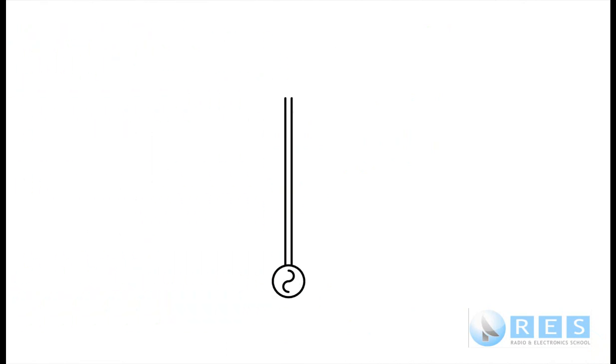Now let's have a talk about some of the antennas that you're going to need to know about for the standard assessment. Before, and I've just rotated this image, before we were discussing if this was a transmission line it won't radiate. If it was a parallel line it won't radiate because on each leg of the line the currents are equal and going in the opposite direction. So any magnetic or electric fields they generate are cancelled out by one another. With coaxial cable it's the outer braid that prevents any radiation from the transmission line.